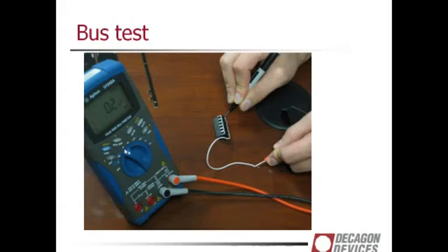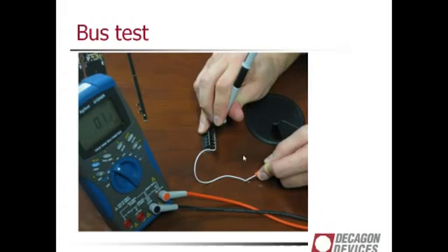So what you're looking for is a high resistance, or someplace where you're just not getting good contact between the sensor port and your line. You'll want to go through and check each individual port. So check this terminal, check all 6 of these, and make sure they're getting good continuity with the full data line. Just remember that a problem in one of these ports could be a problem for all of them.